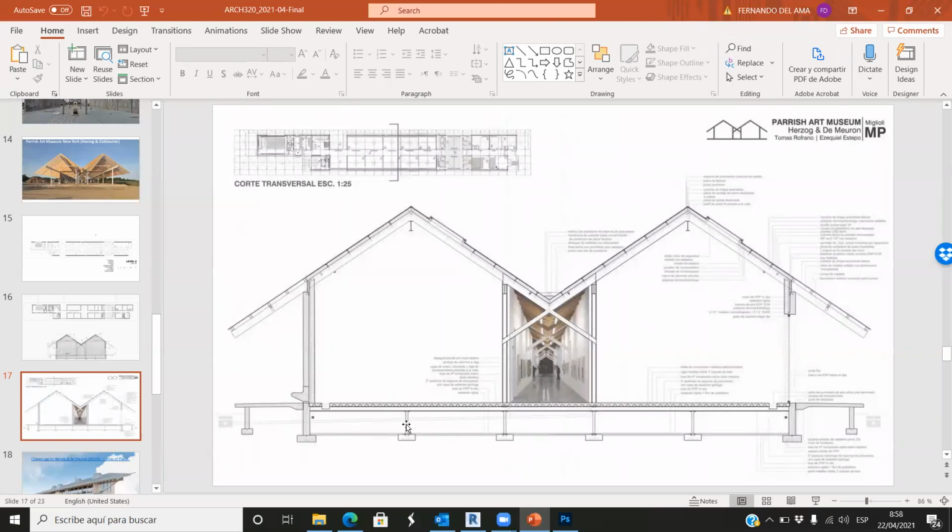I would do this with concrete. I would start the wood structure here, at the concrete slab, and I would do this with concrete and the footing. So there will be columns. This will be a wall with a wall footing, and those would be columns with isolated footings, and that would be another tiny retaining wall with another footing here.